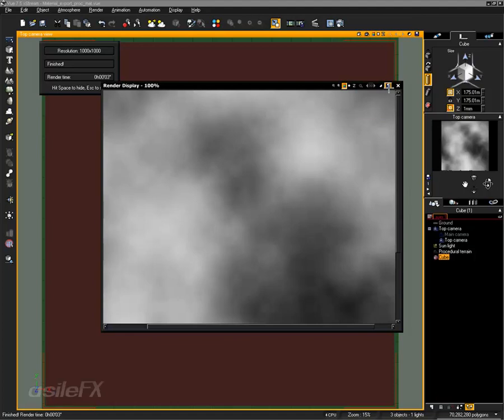So what we could do is save this as a 16-bit TIFF, or you could use HDR or EXR format, and then have a really nice displacement map, something very versatile for export or use directly within the program in view still in order to create different material maps.